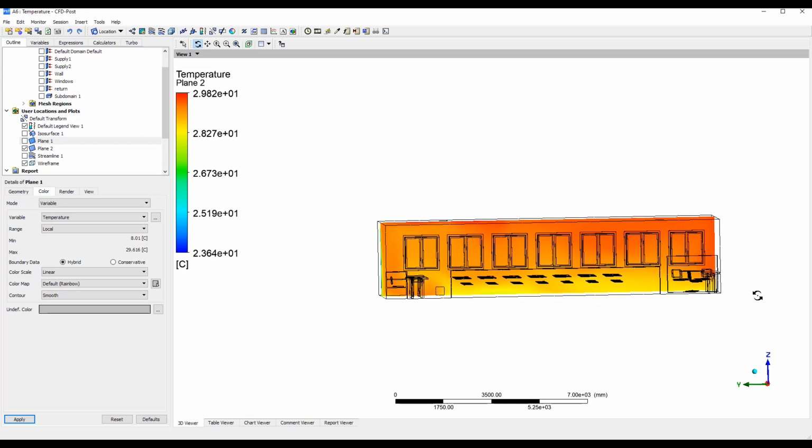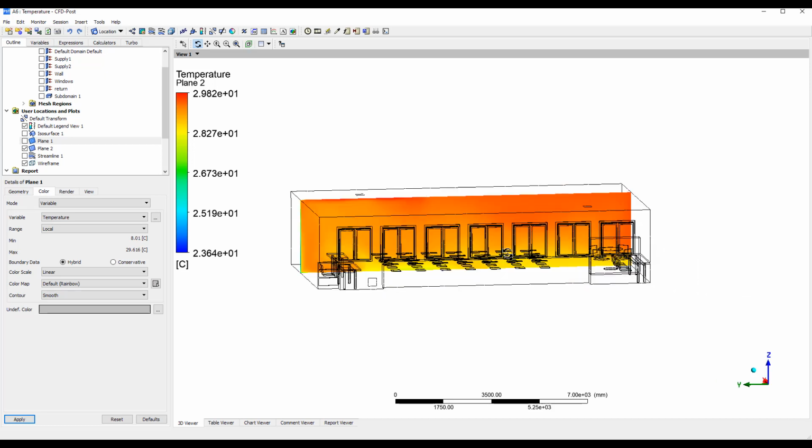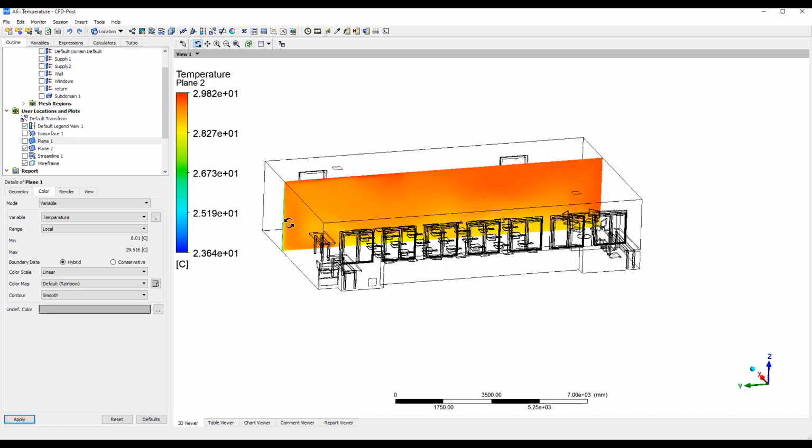So this is a quick example to show you how putting all the things we've done together. Now we included temperature, so we can predict the heat performance of the room. We can put in realistic diffusers, realistic boundary conditions for our windows and walls, and natural convection, and the rest of it all simulated. So a quick example of setting up these simulations.